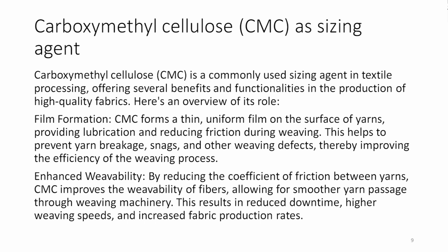Film formation. CMC forms a thin uniform film on the surface of the yarn, providing lubrication and reducing friction during weaving. This helps to prevent yarn breakage, snags and other weaving defects, thereby improving the efficiency of the weaving process.